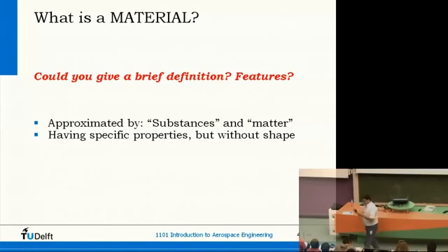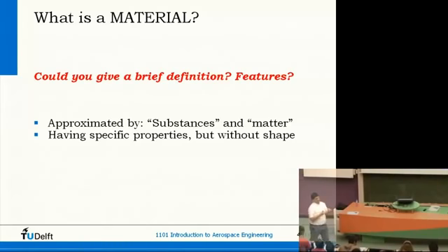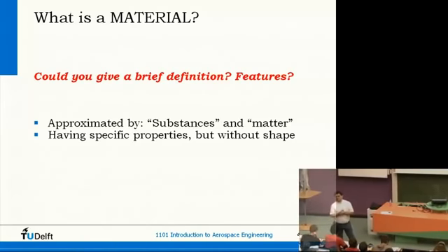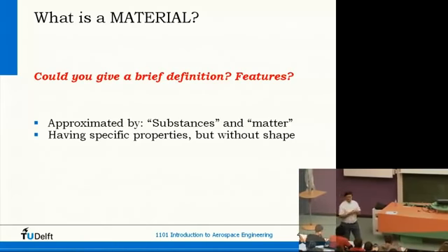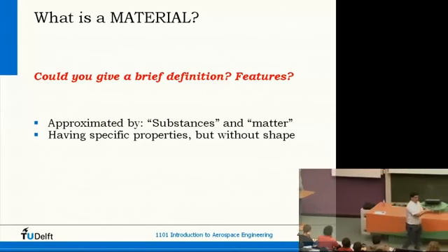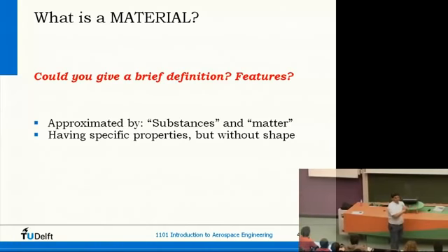We can talk, for instance, about the strength of a material. We can also talk about the strength of a structure. If we talk about the strength of a material, we can zoom in as far as we can, and still that material has the same property. For a structure, the strength is also related to its size, to its dimensions. Small structure has small strength, large structure, large strength.